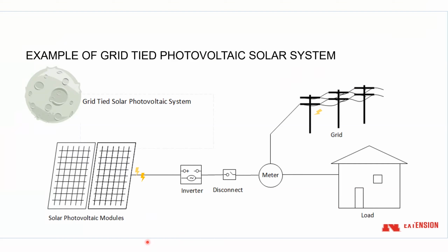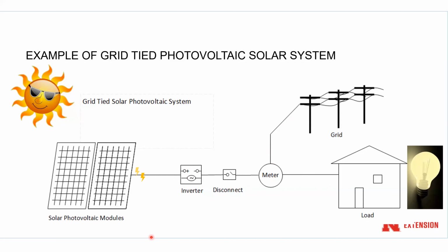So let's think about a scenario here. We have a house connected to the grid, and we turn a light on; it's nighttime. The grid electricity flows to the load. We're paying retail rate for that. The sun comes out, and the electricity is flowing from the solar to the load. That is offsetting what we are buying from the grid. That's also worth retail because it's offsetting what we're buying from the grid. Finally, we go to work or something, turn off our load, and the electricity flows out to the grid. Then that is excess generation. And now we have to really determine: are we on net metering? Are we on net billing? Are we on buy all, sell all, to figure out its value?